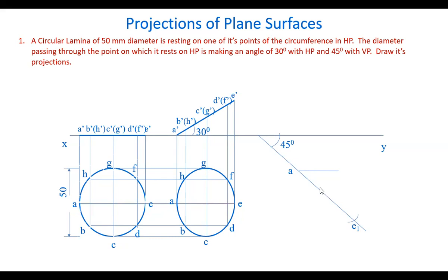Okay. Now draw a line, the locus of E in the top view. Okay. Now take this shortened length AE as radius, A as center, and draw an arc. This intersects here the locus at a point. Call this as E. Now join AE. AE is joined here, and this is the actual apparent angle. That means this AE is now appearing at this beta angle, even though it is making only 45 degrees angle with the VP. This AE line appears at beta angle, that is apparent angle.